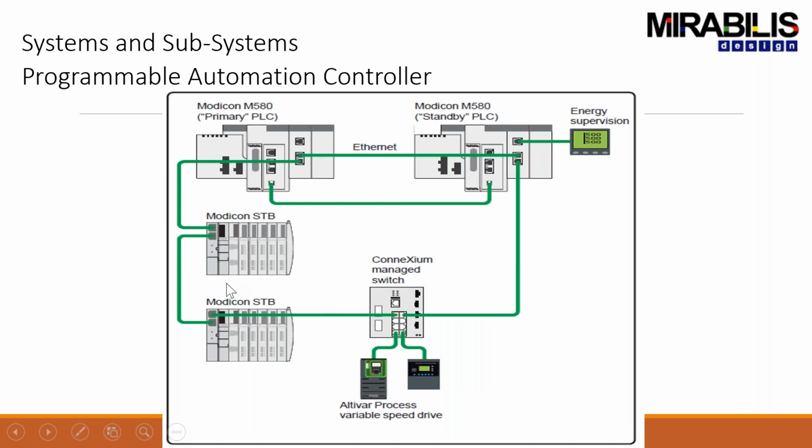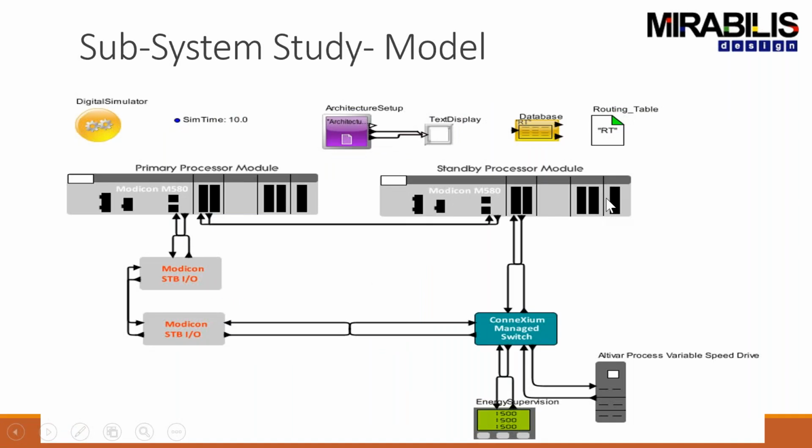So when I'm looking at this overall subsystem, I've got the processing units here. I got the network topology. I got these sensors that are generating traffic. I got a controller, and I got something that's looking at the power management. So this would be a model that you'd want to construct in an environment like VisualSim for doing architecture exploration. So you'd set up your processor modules, you set up your IOs, and of course the switch manager right here.